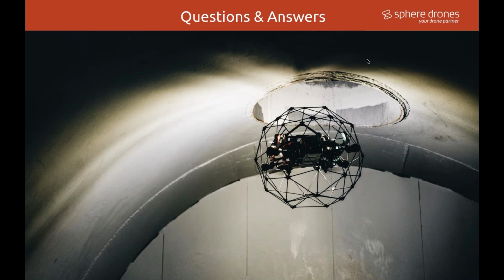But it is sort of different using Elios 2 rather than other drones where you would plan your flight on software and then just push a button and it executes the little grid pattern as you would have it for outdoor stuff. So you have to keep pointing. I mean, you'd have to really work the sticks to keep pointing the camera and the drone at the things you want to capture.